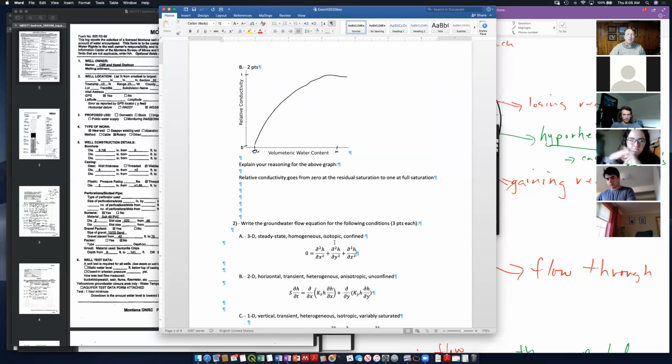Relative hydraulic conductivity was one where I got quite a bit of different answers. Anyways, a lot of people had a curve that looked kind of curved the other way and was asymptotic to porosity and basically exponentially increasing. All right, the maximum relative hydraulic conductivity can get to is 1. So it's going to go up, hit 1, and stay at 1 after porosity.